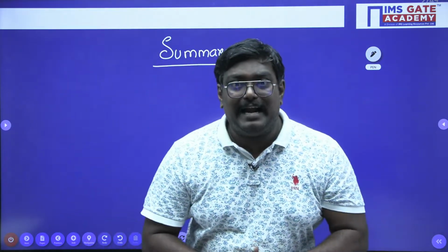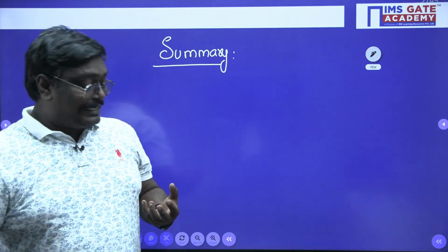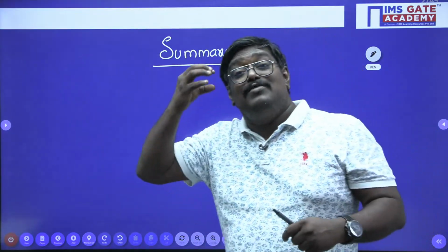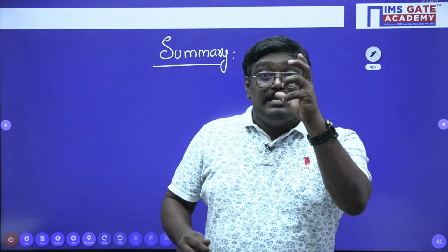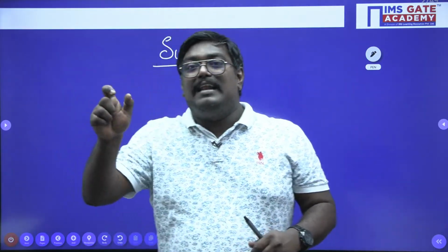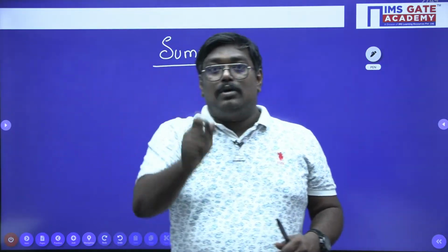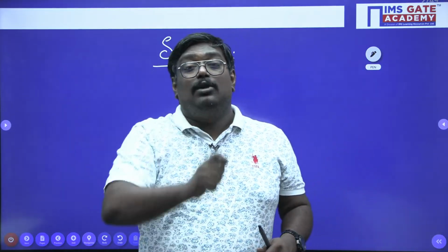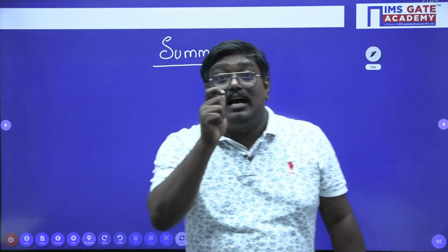And remember, my dear students, the American Association of State Highway and Transportation Officials, the Public Roads Administration and the Highway Research Board wanted to identify the soil which is suitable for pavement. So they classified the soil into 7 groups, named A1, A2 up to A7, and black cotton soil falls under the A7 group. Please note down this point, students: smaller the number, better is the soil for pavement.